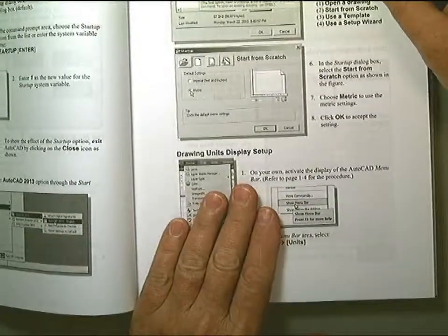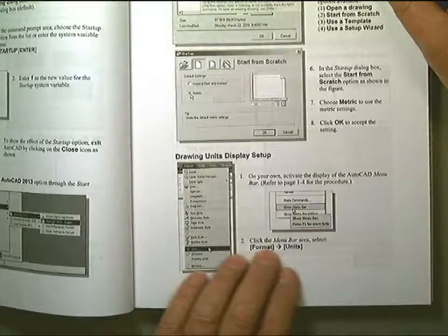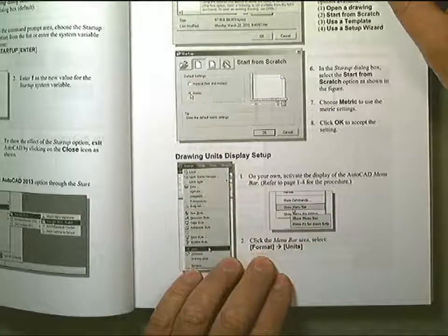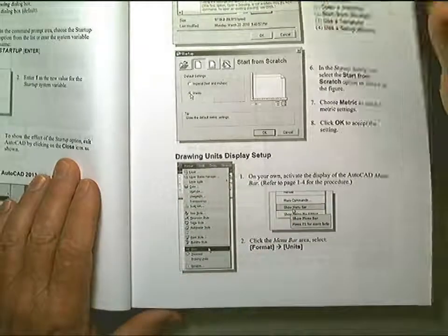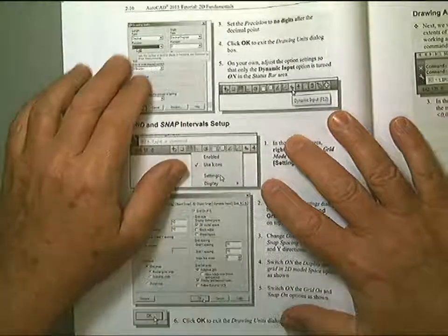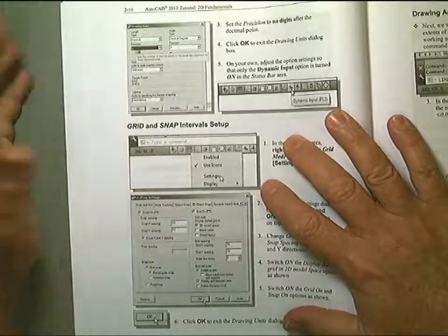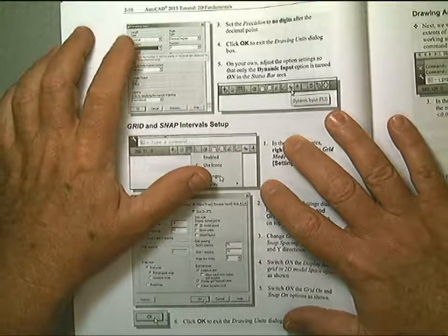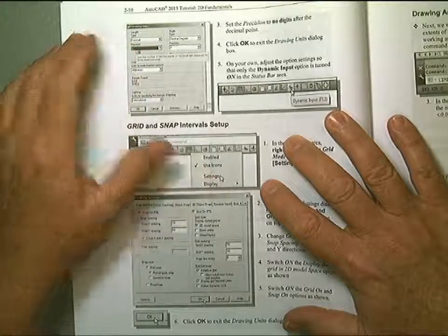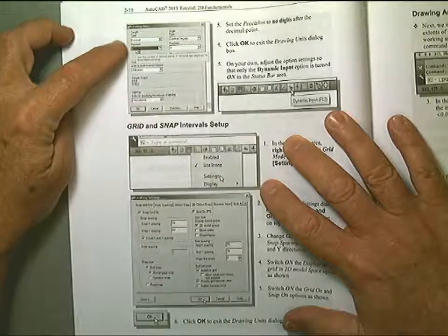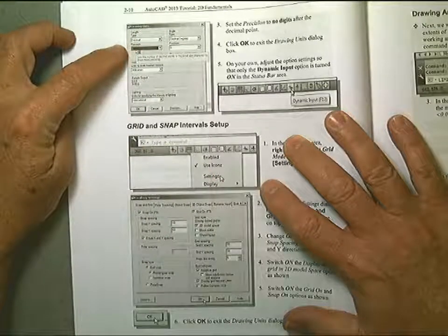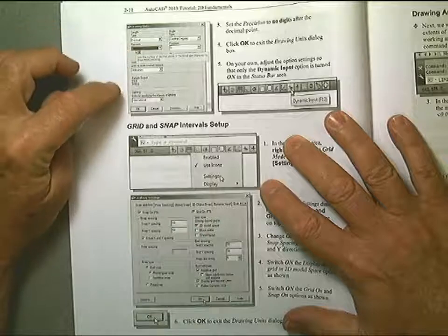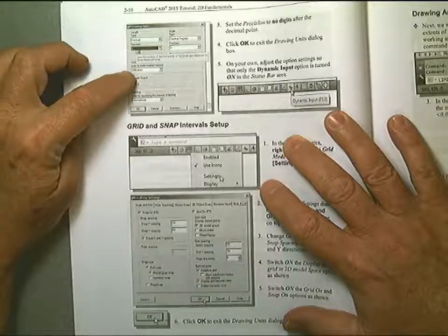Be sure and pay attention to this, that you set up the proper units. The units in AutoCAD are important. Decimal, if you've started up using an imperial or started up using a metric, the basic choice that most people use is the decimal. And you'll set it to, now in this case it's in millimeters.